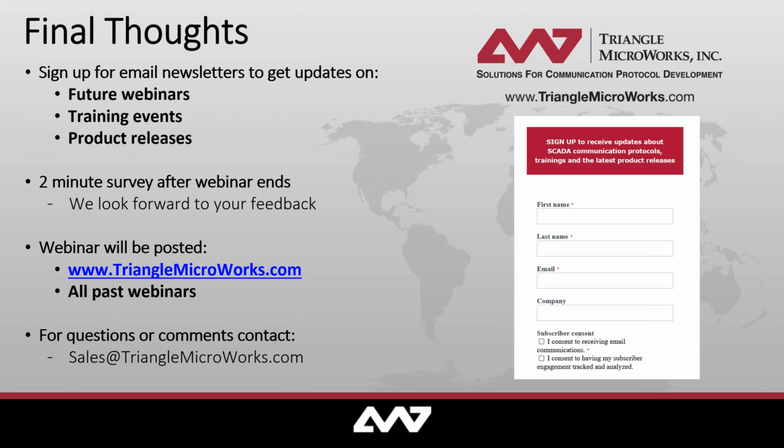The service section in the IED, as I shortly mentioned but didn't go into details, is where the capabilities of the IEDs are described in terms of communication and engineering flexibility. Not necessarily all communication services are required. As an example, sampled values is typically only used by a merging unit that transmits sampled values. So in the service section, the IED indicates what services are supported. So that's one important part.